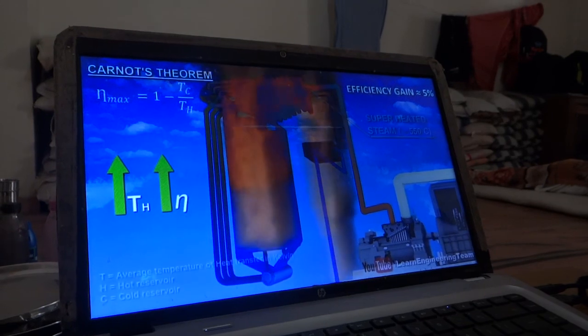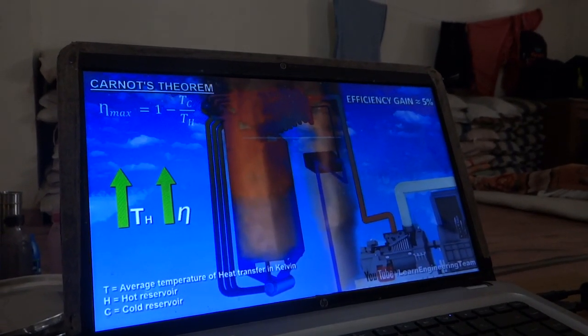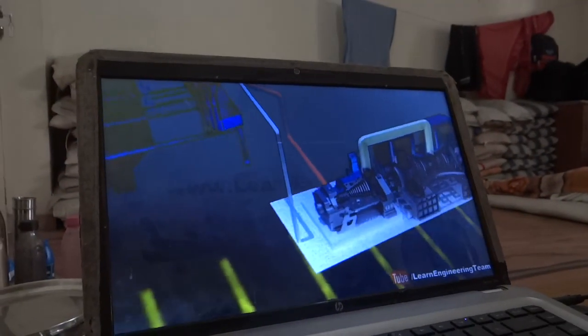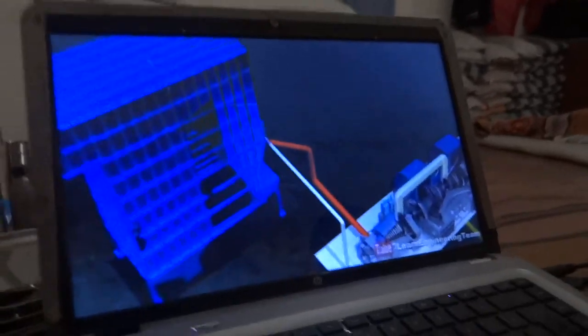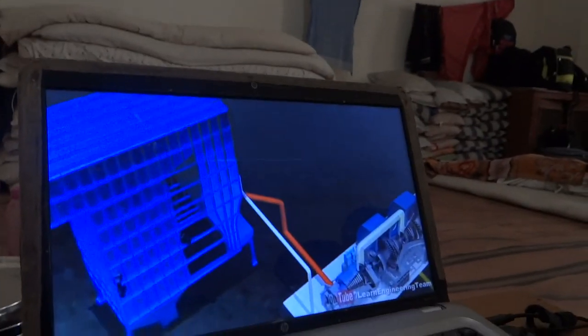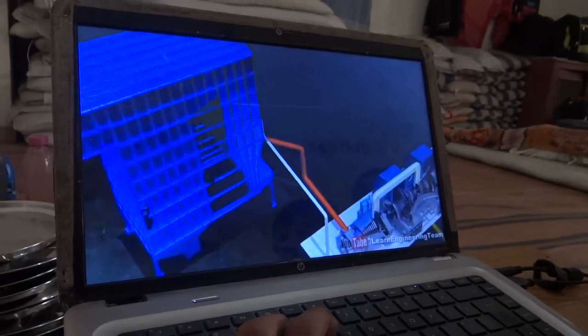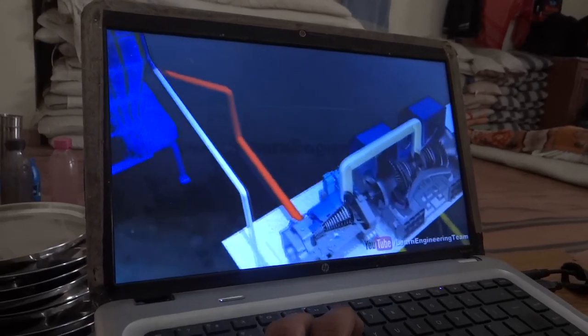Just remember Carnot's theorem of maximal thermal efficiency possible. But the steam turbine material will not withstand temperatures of more than 600 degrees Celsius. So we do not supply more superheated steam. Superheating is limited to that 550 degree threshold.